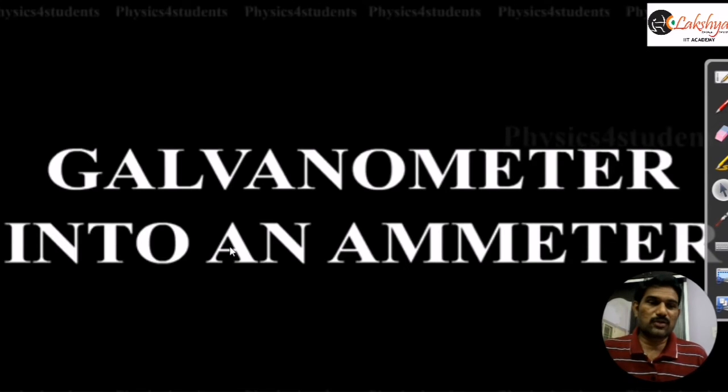The galvanometer into ammeter. So just now we discussed the galvanometer, ammeter and voltmeter. Now let us see how to convert a galvanometer into an ammeter. A galvanometer can be converted into an ammeter and can also be converted into a voltmeter. Ammeter means we need to increase the range, because a galvanometer already measures current, but only a very small current. Now we need to increase the range of this galvanometer, right?